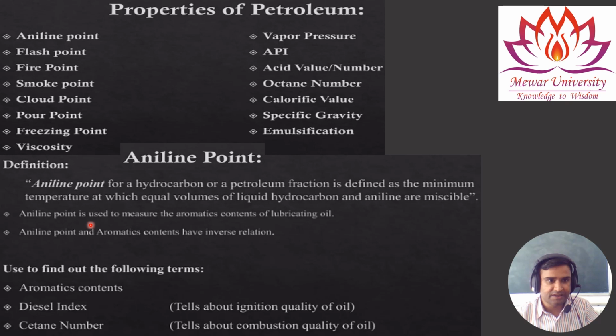So aniline point is used to measure the aromatic content of the lubricating oil, and aniline point and aromatic content have inverse relation. So it is used to find out the following terms: the aromatic content, diesel index and cetane number. Diesel index tells about the ignition quality of an oil, and cetane number will tell you about the combustion quality of oil.